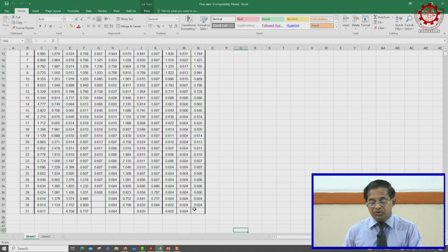So, we have used the hydrologist to get this table, and from this point onward we must use this data to determine what should be our rated flow rate, and also how much energy we can annually generate. That is the business of a hydropower engineer. That is what we are learning from this course: how to use hydrologist data to size our project, that is, determine the Q rated flow rate, and then how much energy we can generate each day, and also what should be the plant capacity, etcetera. We should be able to calculate that. We will go through and see.